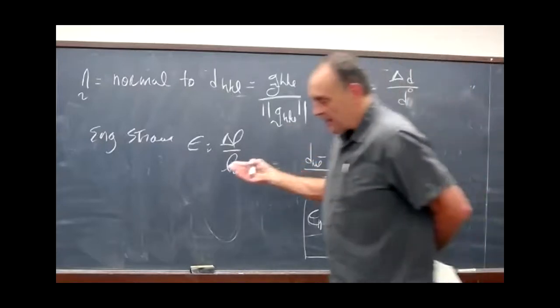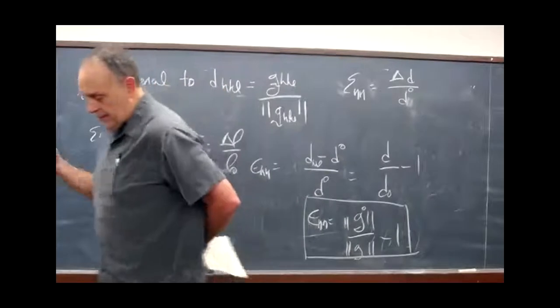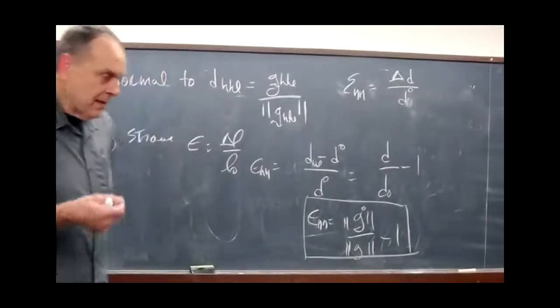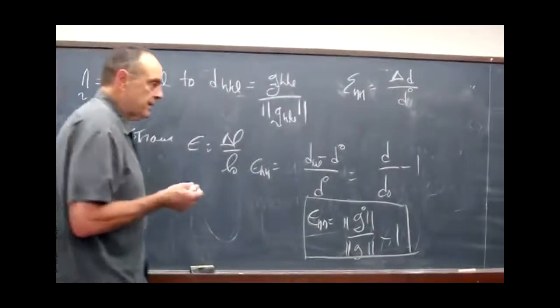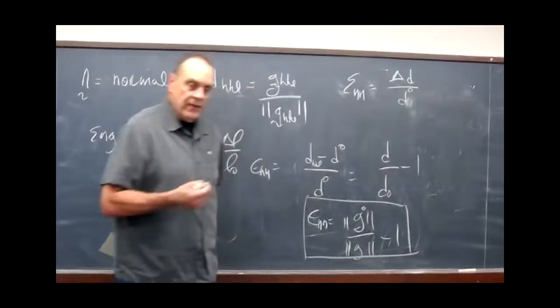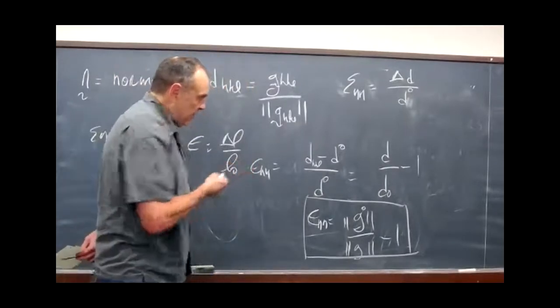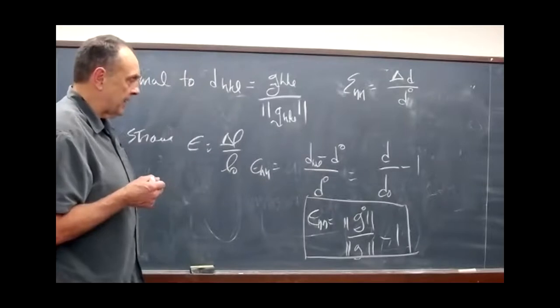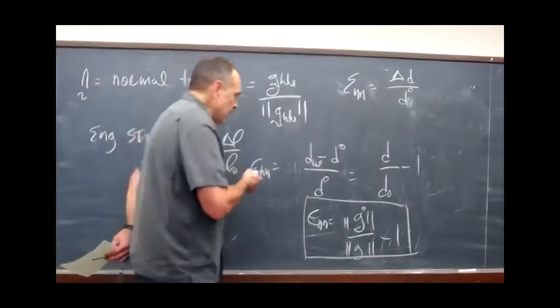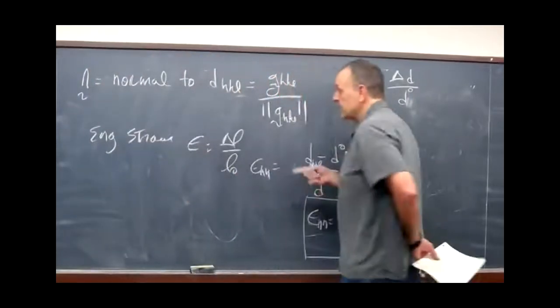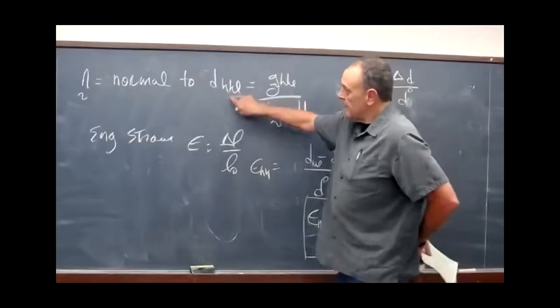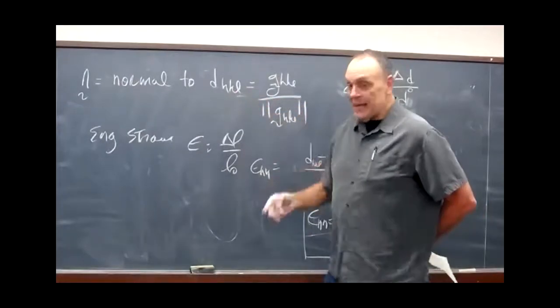So go back and do it again. You have a diffraction spot. You measure the G vector knowing 2 theta, eta, and omega. You watch that spot shift. You calculate the new G vector. And this expression then enables you to calculate the normal strain associated with this particular set of lattice planes in a particular direction.